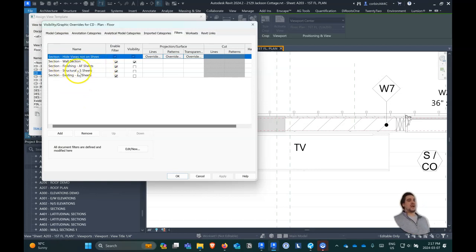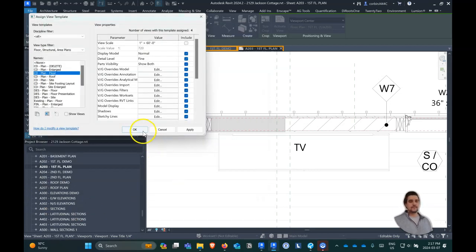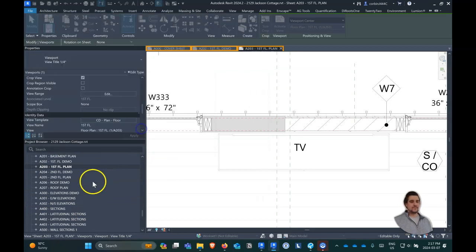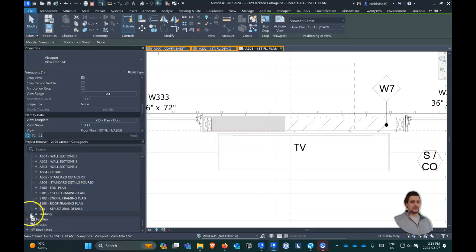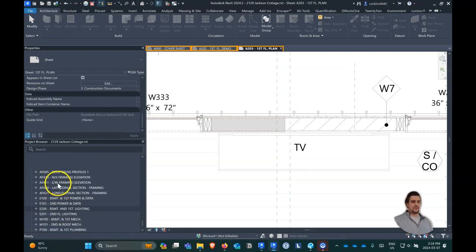So if we call the sheets AF, for architectural finishing, and we have the AF tag as the sheet number, it'll automatically not show those section tags on our core construction drawings. Filters are very cool. It's like a whole other world. So when you say AF sheets, you mean sheet numbering? Correct, as AF. Okay. Yeah, so here are all our finishing sheets.